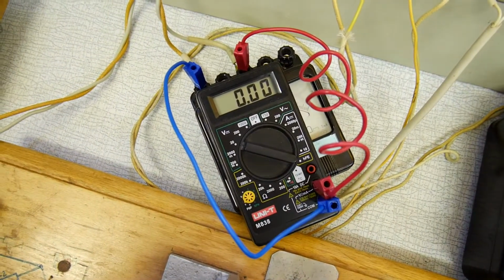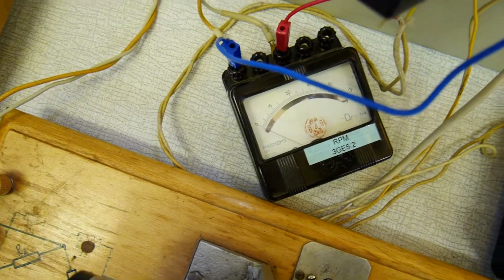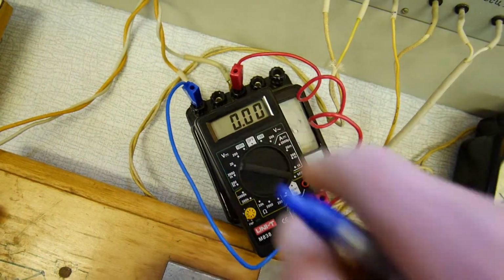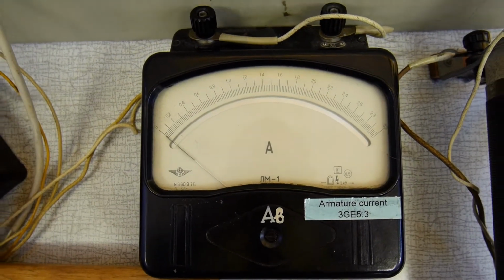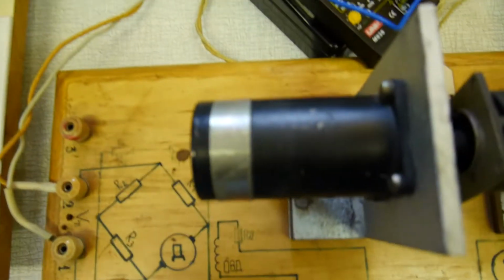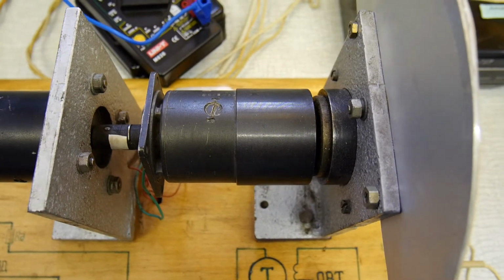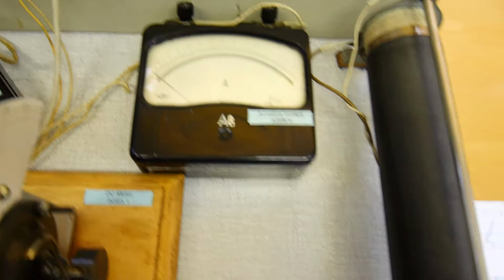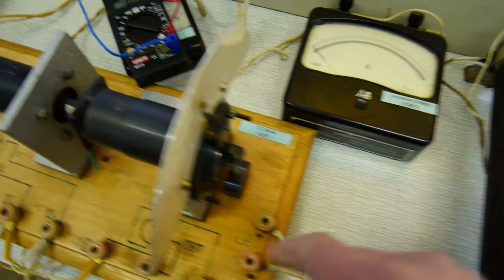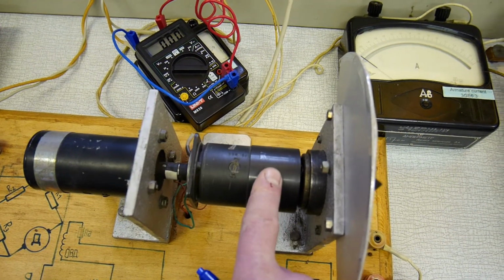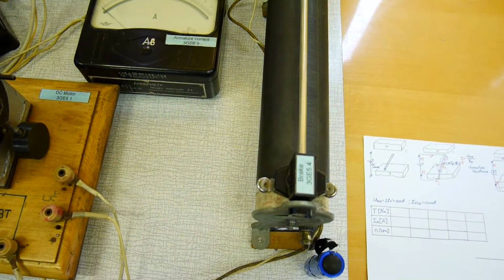This multimeter will help us to see speed. 1 volt is 1000 RPM. Actually, it is connected to the voltmeter, but I suppose it will be better to read from here. And this ammeter will show us the current which is consumed by our DC machine under test. The current which flows through the brake is not shown here. This rheostat helps me to control this machine, which can add or subtract. So I can add or subtract more, or I can add or subtract less.